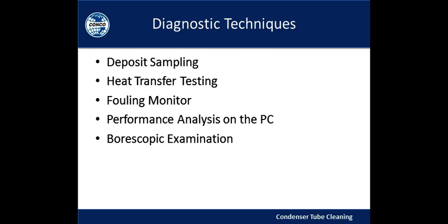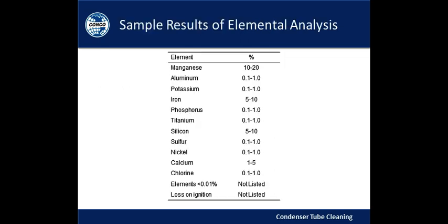If a deposit is present, clean the condenser tubes. So it's quite straightforward, and that performance test code is largely based on the idea that you're accepting a new condenser or evaluating the performance of an operating condenser. But we know that the presence of deposits will result in a compromised heat transfer.